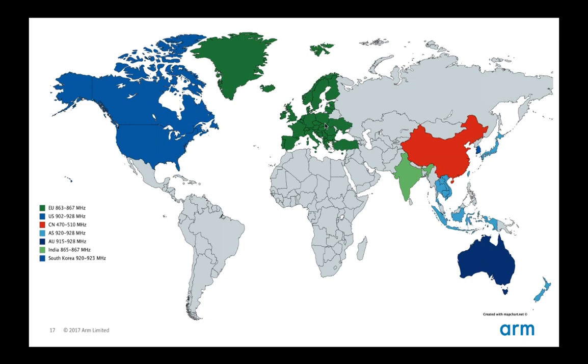And of course, you can also use LoRaWAN in other regions that are not colored here. For example, here in South Africa, the European frequency plan is being used because South Africa is a member of the ETSI. So ETSI countries follow the European plan, and FCC derivatives are following the US 915 plan. So you can basically use LoRaWAN across the world with typically 3 different radios, and currently more regional parameters for other regions are being specified by the technical committee.